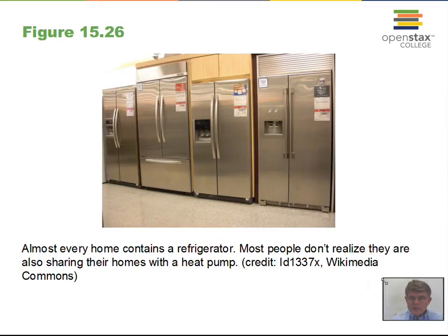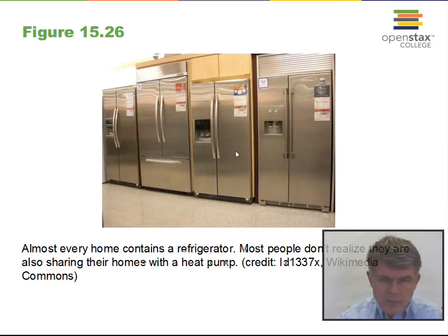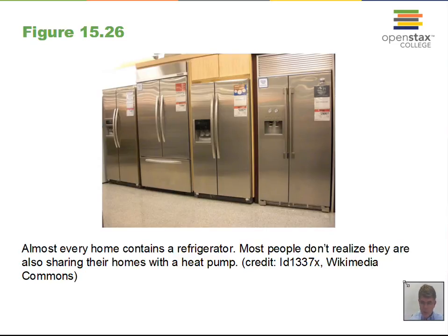This video will discuss heat pumps and their coefficient of performance. So a heat pump is a device that moves energy from one location to another, where the movement is from the cold region to the warmer region. So this is not spontaneous movement of energy. The laws of thermodynamics say that will never happen, that spontaneously energy will move from the cold area to the warmer area. But we can create heat pumps that do this.